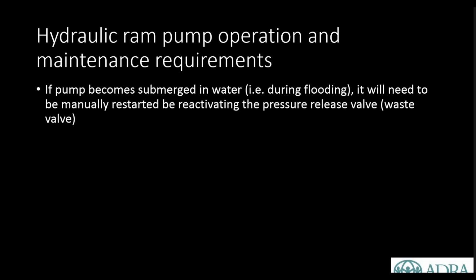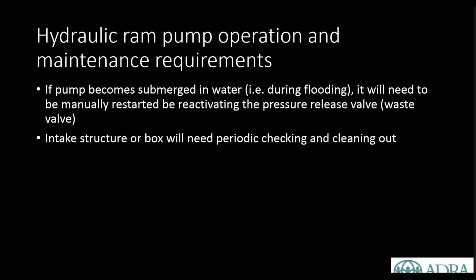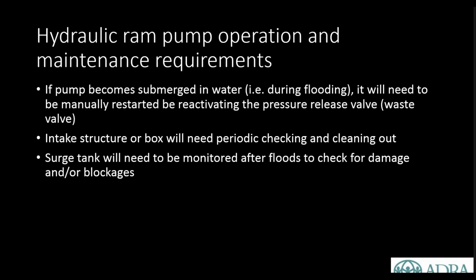So operation and maintenance. If the pump becomes submerged in water, such as when it floods, it needs to be manually restarted so that the pressure release valve or the waste valve can be reactivated, and then the pump needs to be started in that way. The intake structure and box needs to be checked and cleaned out every so often, and particularly after periods of flooding. And the surge tank will need to be monitored after floods to check for damage as well.